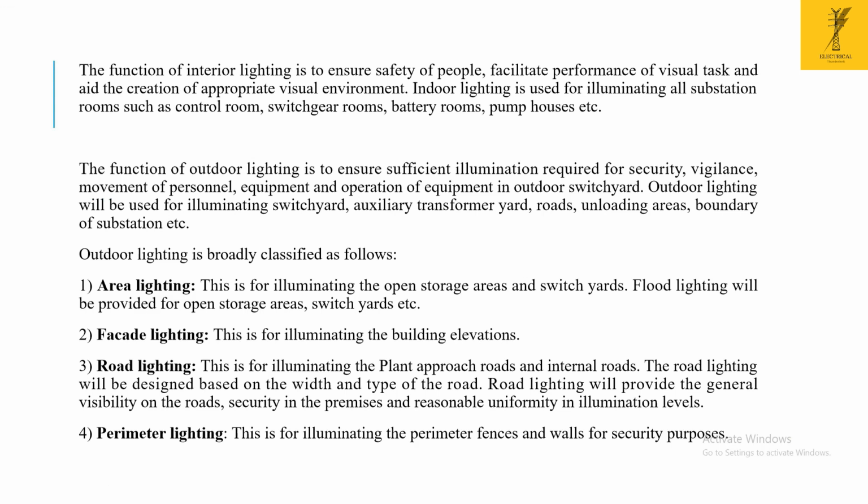Outdoor lighting is required for security, vigilance, movement of personnel, equipment, or operation of the equipment in the outdoor switchyard. Generally, we have to consider the outdoor lighting. Mostly, we have to focus on the auxiliary transformer or power transformer areas, breaker areas, as well as roads, unloading areas, boundaries of the substations, etc.